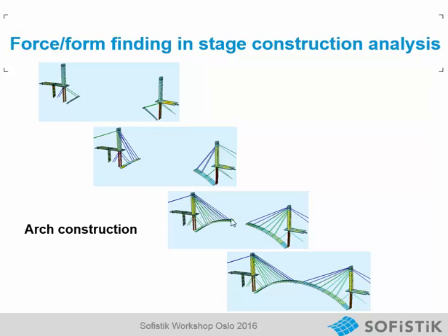You can just optimize the deformation with the precamber. Very easy and cheap. So if in your analysis the two cantilevers do not fit together, it is really not a problem. Don't care about this deformation.